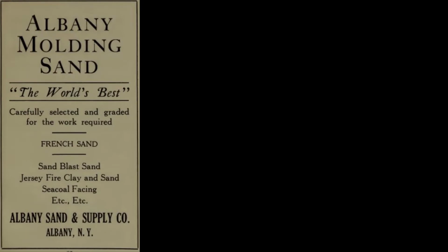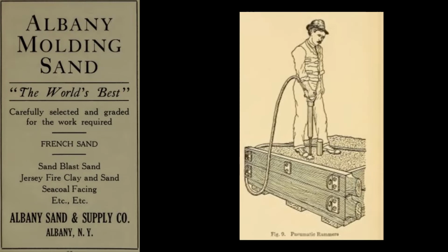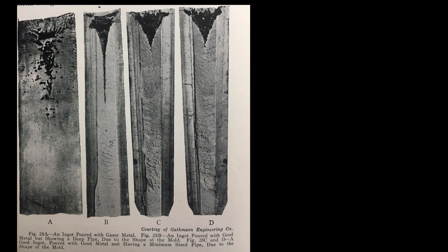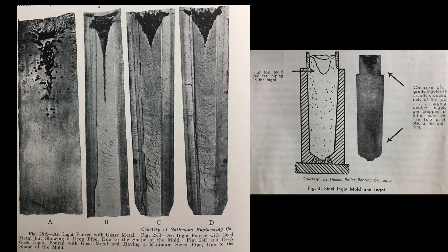The surface finish of a casting is going to be a result of whatever the mold is made out of. So if it's a sand mold, it just depends on the coarseness of the sand. If it's extremely fine, you'll have a good surface finish. If you have pebbles in there, it's going to be an extremely bad surface finish. If you're doing die casting, in which the mold is made out of metal itself, then it's going to take on whatever the surface finish of the mold is, right? So when they make anything optical grade, the mold is mirror polished, right? There's no scratches. It's like a super finish, 16 microinches.